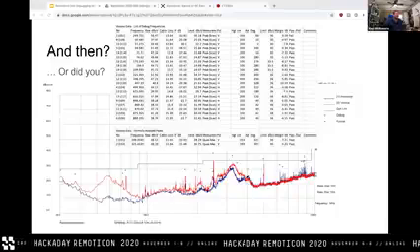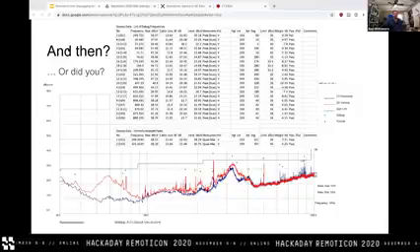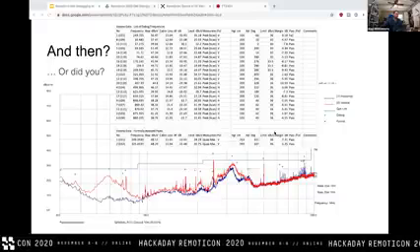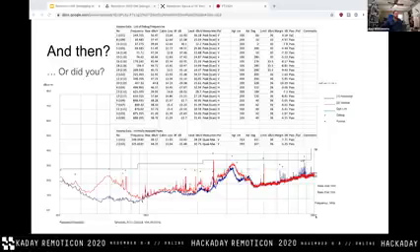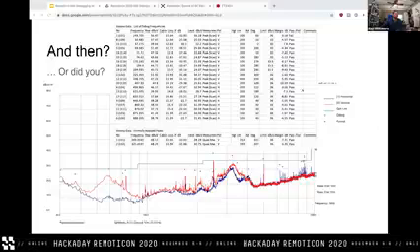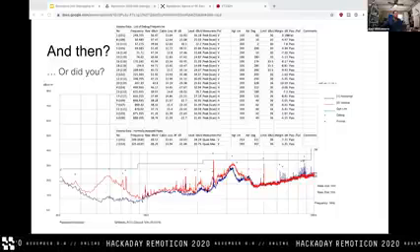And I guess I jumped the gun describing all of that because the next slide was, or did you actually fail? And the answer was on a lot of those peaks, no. This is an example from that same 30 megahertz to 1 gigahertz spectrum, where the product has at least one, actually in this case, there's only one limit line violation at that 250 megahertz.